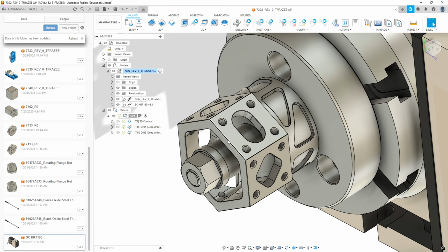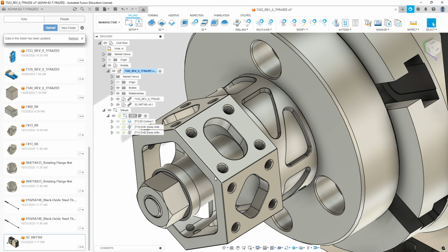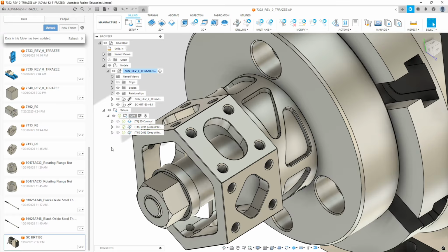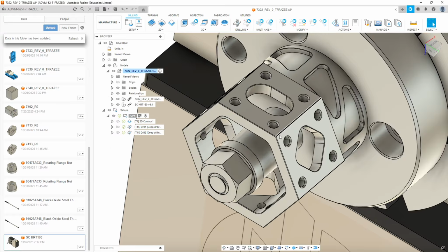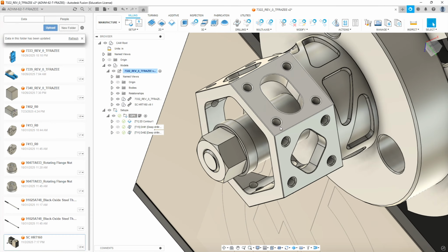Now, what other features happen 6 times on this part? Well, we have an edge break here that we're going to want to machine. Actually, we're going to hold off on the chamfers. We're going to do those towards the end, that way we're not changing tools a lot. So we got tool 1 cutting the flat. We have our countersink cut by the spot face. And then we have our drilling cycle. Okay, so those are all the features we want, for now, to create a pattern for.